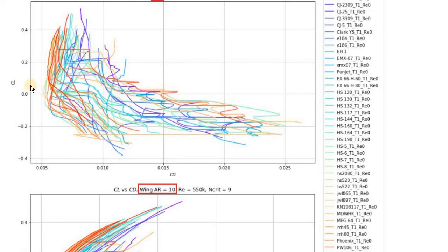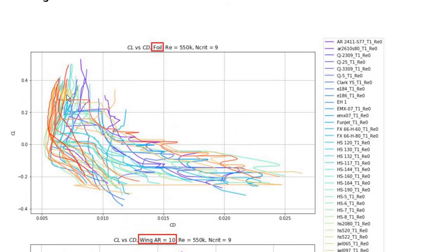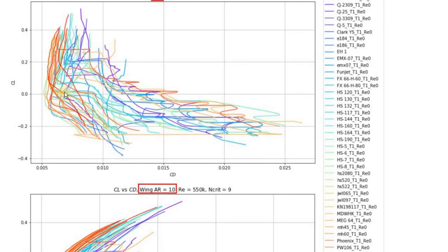But I have to add one comment: we actually need lift coefficient, as we remember, 0.025. So 10 times less, somewhere here. So we need very small lift coefficient, and for the small lift coefficient, the wing effect has zero effect. There is no wing effect for small lift coefficients because the induced drag produced by the wing is proportional to the lift coefficient squared.